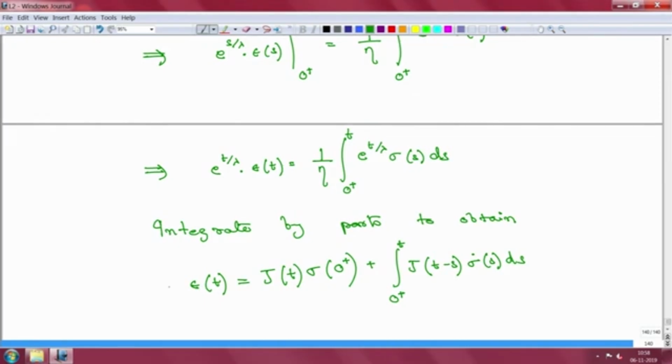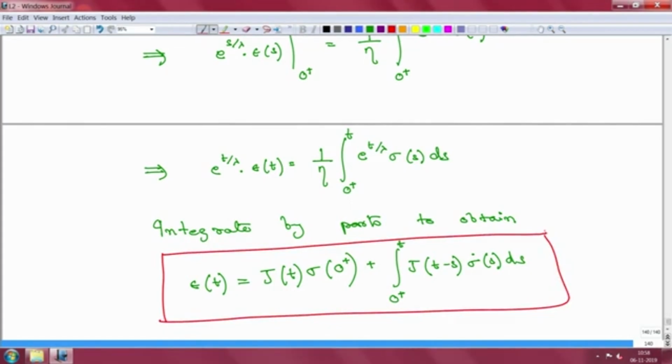Okay. This is rather interesting because the two creep functions are very, very different, yet when you try to find the strain from the stress history, you end up with a functional form that is exactly the same as the Maxwell model. So this indicates that this particular functional form that I have boxed in red is a more generic equation that governs such models.